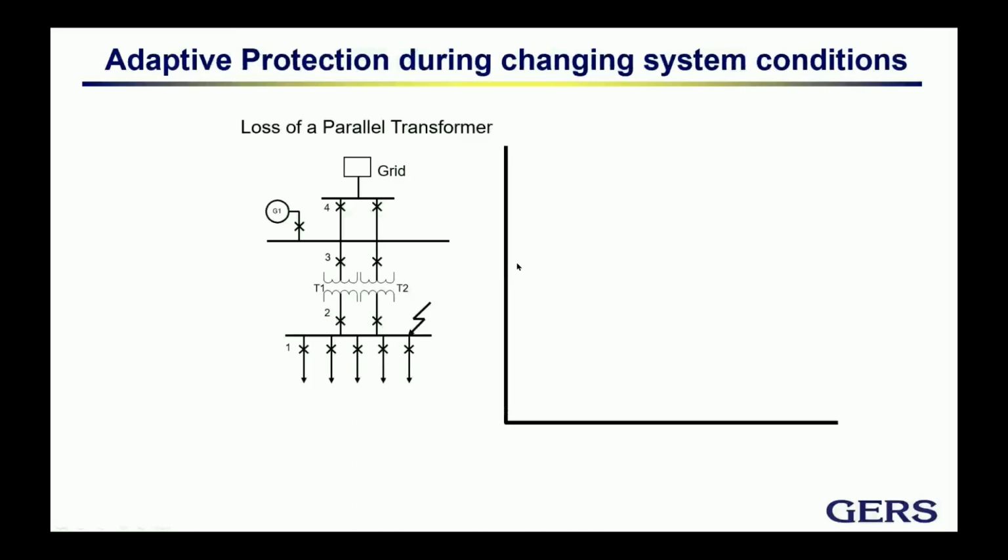As you know, what we normally do is the calculations of the fault current here to determine the setting of the instantaneous, and we pick the smallest dial available, considering, of course, the cold load pickup. So for that very relay number 1, let's suppose that after you apply your criteria to select pickup or tap, you pick the lowest dial, if that is allowed by the cold load pickup.